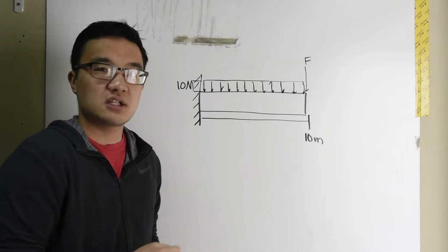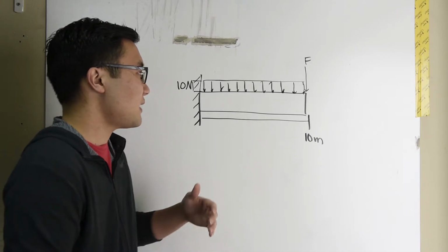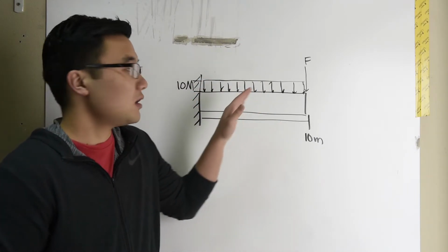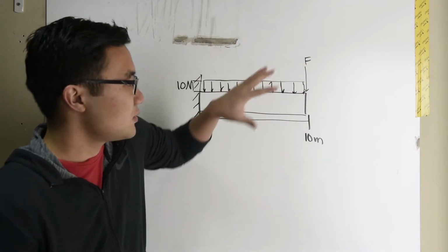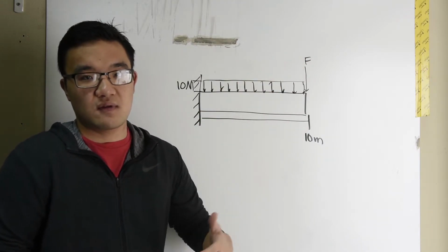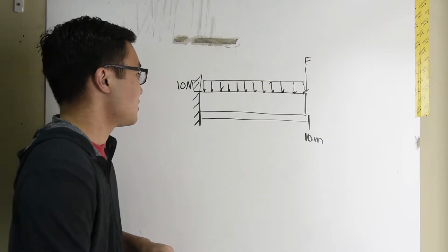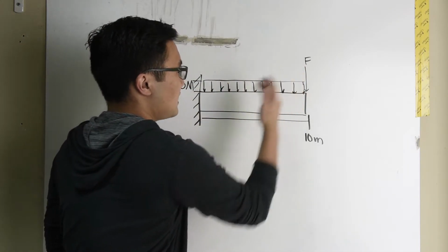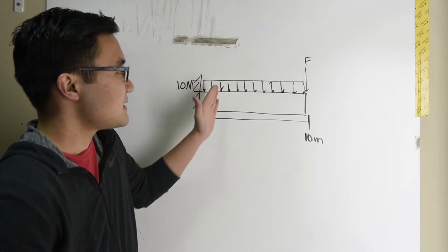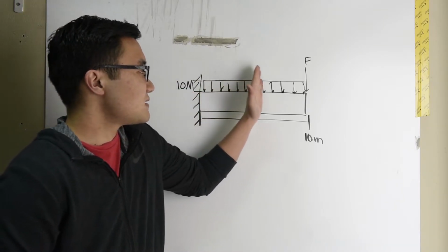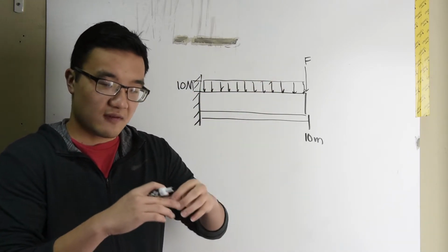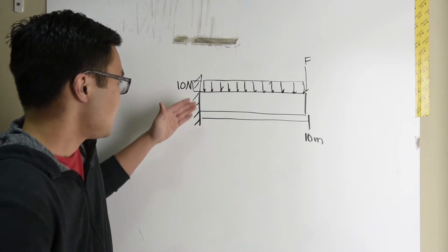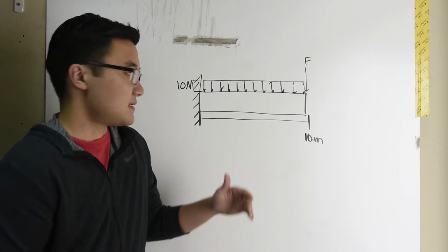You guys have all done integration, right? If I want to figure out what the summation of all of this load is, I'm going to integrate everything under that boundary condition, or under that upper bound, right? As I move from left to right here, I'm going to continuously sum every single segment until I come up with what the final distributed load is on the beam. So in this case, you can probably guess already, but it's quite simple.